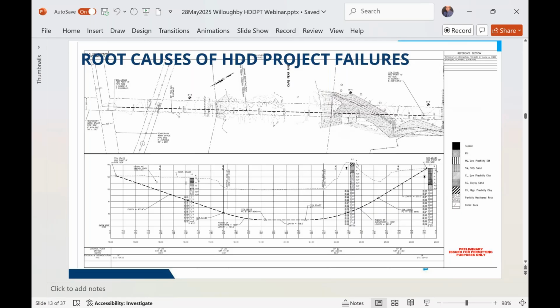It's just another example right here. You can see right here is a 48-inch sanitary sewer, and you can see that pipe there is 10 foot below that sewer. Again, that dashed line is the pilot hole. Now, I think this was, if I remember right, 8-inch pipes. So you're probably looking at around a 14-inch reamed hole.